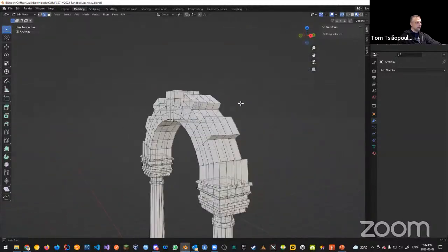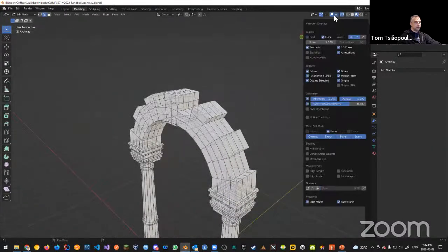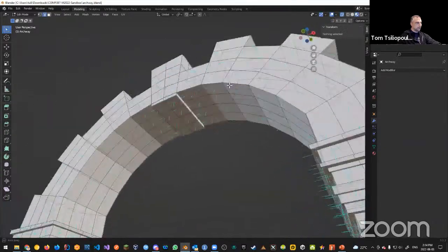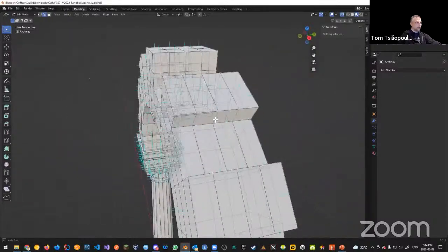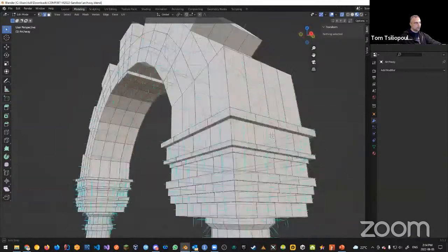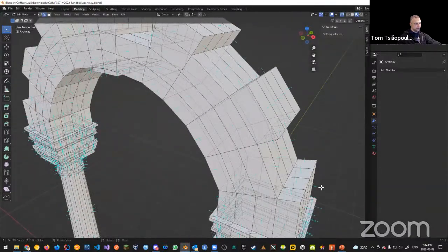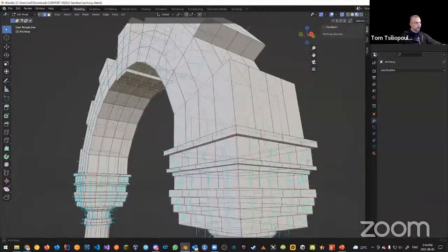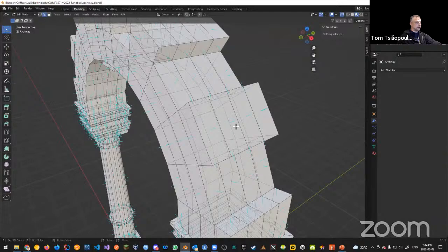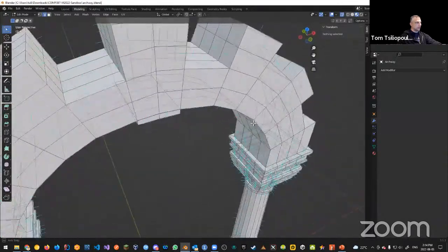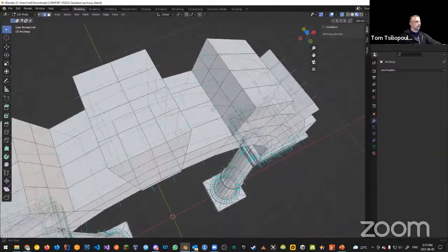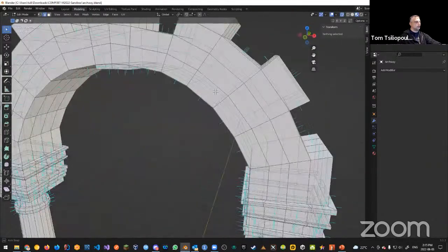Okay. And also let's check to see again with the normals. Let's make sure that the normals are all outside and not pointing on the inside. Don't want the normals on the inside. So I'm just quickly doing a scan of the normals on the outside of the model, just to make sure we can see those extra faces I made, that they're all pointing outwards, not inwards, because that would be weird. Maybe I'll miss it. And if we do, we have to recalculate on the outside. But I think we're pretty good in terms of the way it was all done. Just looking at it from all angles here, just to inspect the model. I think it's pretty good.